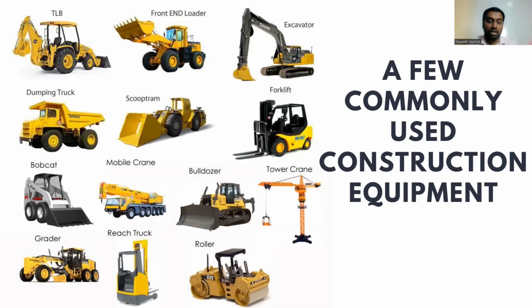Next, we look at dumping truck. Once the excavator excavates, the material will be put in a dumping truck if you are going to transport it for a longer distance. If it is just from one part of the site to another part of the site, we use loaders. But if you are transporting material over a long distance, then it is preferable to have dumping trucks. Dumping trucks cannot have loading options, but they do have unloading options because it has a lever which inclines and through gravity will dump all the materials.